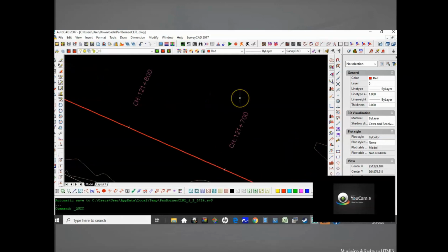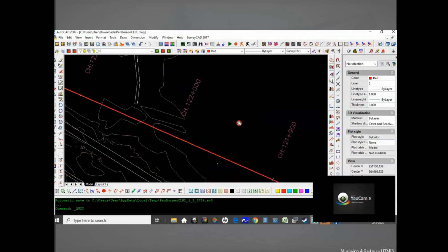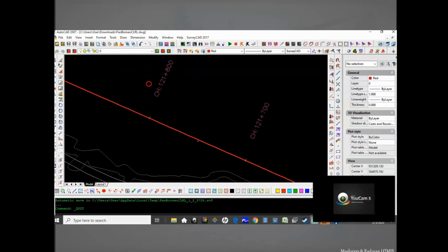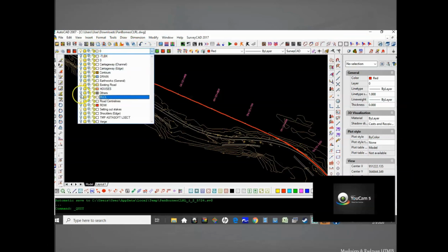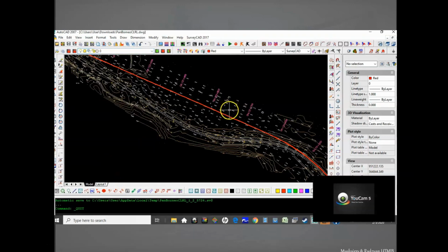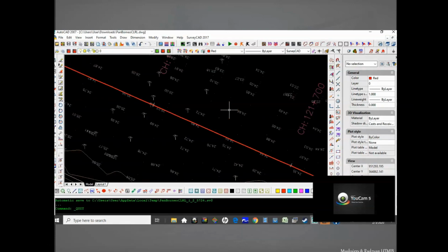And I think in this case, the interval was 100 meter. That's the alignment, that's the center line. Now once we obtain that, we can basically get what we call a long section. But to get a better representation, we then conduct a detailed survey along the alignment. Those numbers represent spot heights, and if you could see, those spot heights are taken basically at right angle to the alignment.